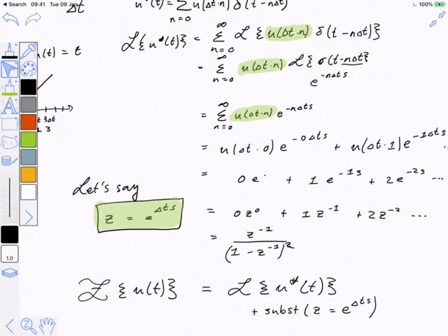And this is commonly known as inverting the Z transform. An important point, which is the last point here, is that unlike the Laplace transform, if I give you a Z transform, you cannot tell me what the function of time was. It is not possible. Partly because most of these functions on the left-hand side of the table are not band-limited functions.